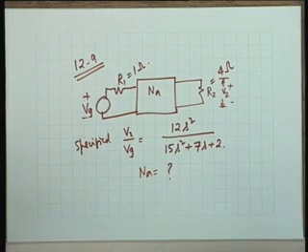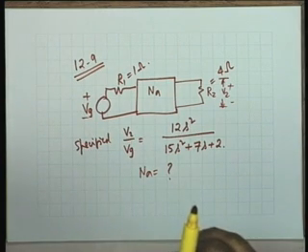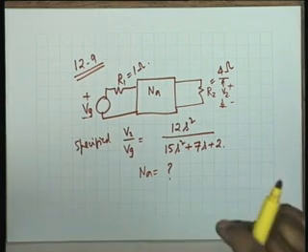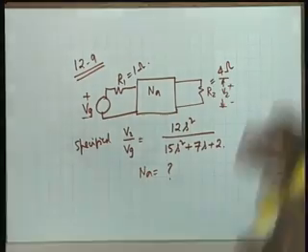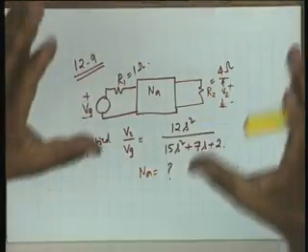Any other suggestion? Should we convert the Vg and R into its Norton equivalent? Why aren't you thinking in terms of Na? What is the possible structure of Na? How many zeros are there? Transmission zeros, 2, and both of them are at the origin. So it must be a very simple network. Can you guess what the network would be? A series capacitor and a shunt inductor. That's it. A series capacitor and a shunt inductor. This is C, this is L.